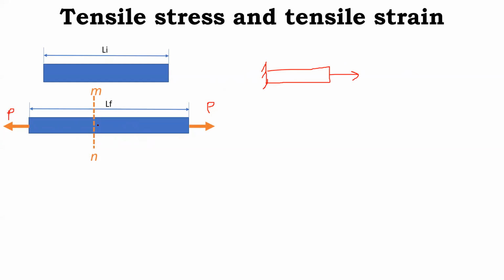So it is like this. This is basically the free body diagram for this. So we remove this wall and we put this force which is caused by this wall. Now we cut this. One more thing, and this is under the equilibrium. So if you consider this thing, this is completely under the equilibrium. This is a bar. This is the load acting in the left direction, load acting in the right direction.